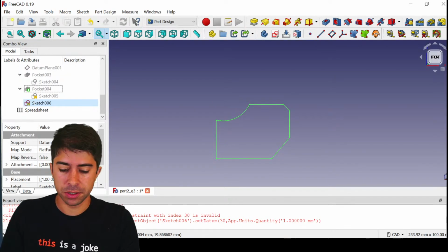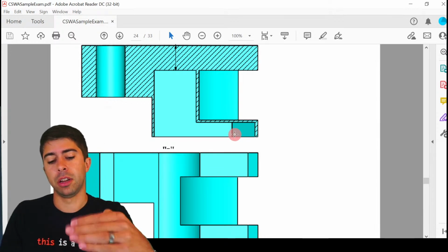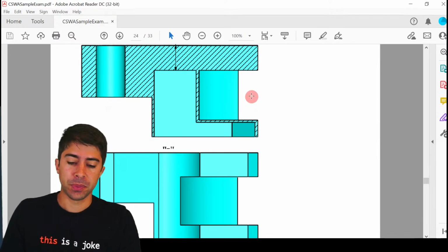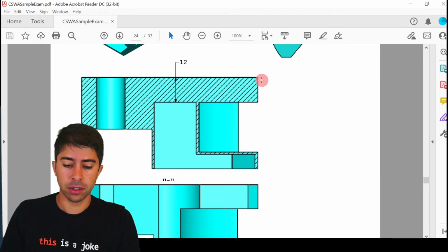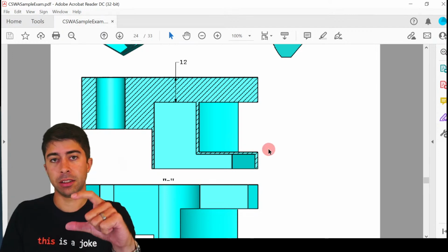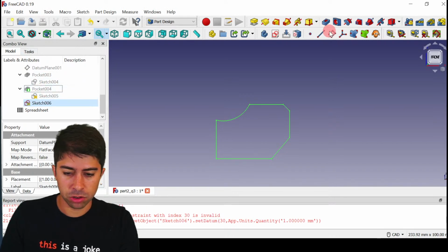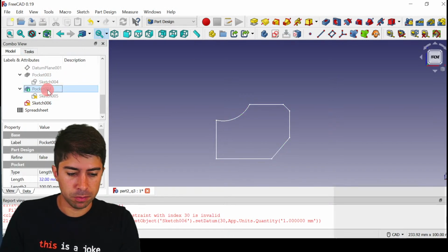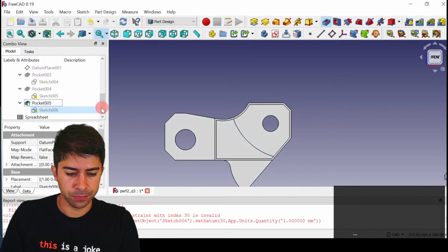And there's that part. So looking at that, that needs to be cut only 1 millimeter to the back. So to do that, we're going to take our C, -12, -24, -1 to get the depth of the cut we want. So we're going to say sketch. Let's make our pocket visible again. Sketch cut.